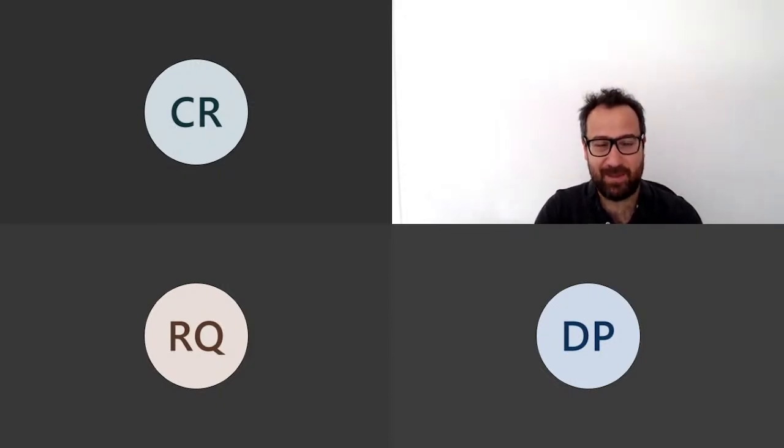So typically, in very early stage monitoring of such systems, you will have frequency controls. So you will be trying to read the frequency of the system to see if there are any early warnings, of the frequency going to 50.3, 50.4 hertz or something like that.